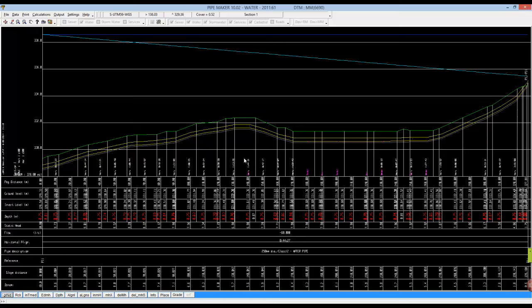Now obviously if you've done a hydraulic design with Area Maker in Model Maker, you will have much better control over your pipe diameters, and you will have to just mimic those diameters. Now we're in the process of trying to implement an automated conversion from irrigation pipes to a string that can be used in Pipe Maker, so that you don't have to go and fiddle and change the pipe diameters.